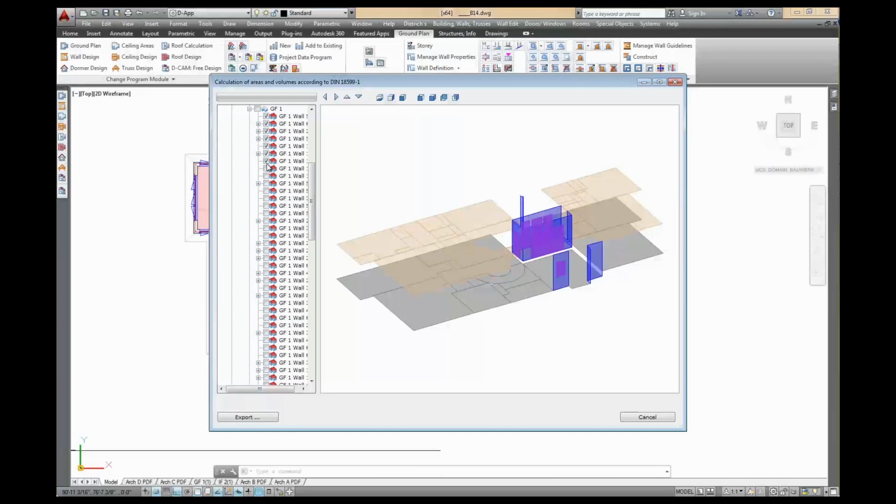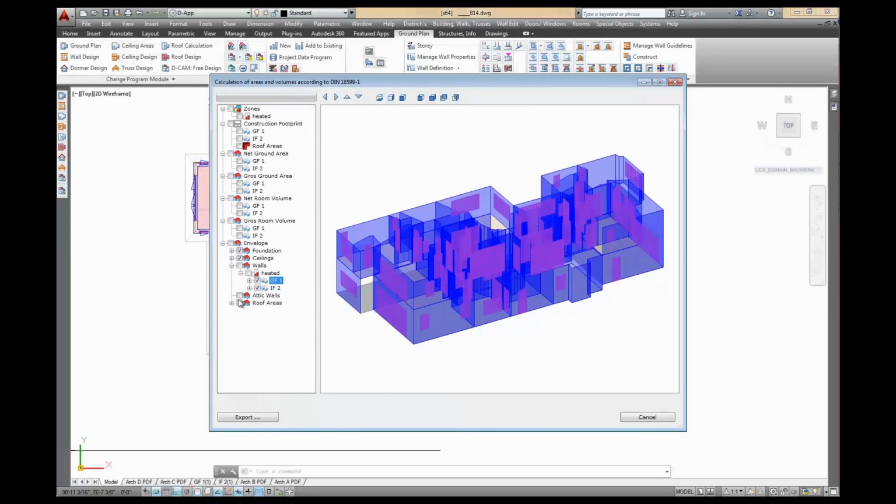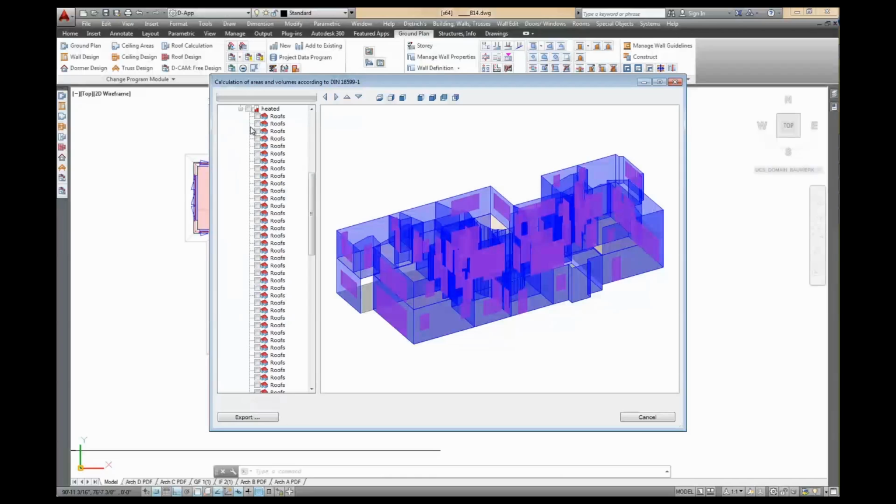And to every one of those components, there's a U value and a heat level for the room behind it. So all that together is my thermal envelope. There's the roof surfaces covering the rest of the building. And that is the envelope that's going to transmit heat to the outside. So this detailed description of the thermal envelope with all the areas and the thermal properties of walls, ceilings and roofs, we generate a green building XML file, which we can then use to generate certificates for different code requirements for HERS, net zero home, or even for a passive house.